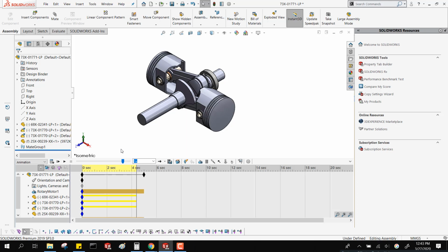Okay, I hear what you're saying. No, not really. What the kinematic analysis is going to do is spin around that axis for you. It's going to give you angular velocities and motion and things like that as to how your assembly is set up. But if you're looking for vibration caused by the motor running or things like that, there is a frequency analysis that you can do. But the kinematics really isn't going to do that for you. Okay, all right. Don't let me derail you anymore. It's fine, not a problem. I already have seen this presentation since I did it without sound yesterday.